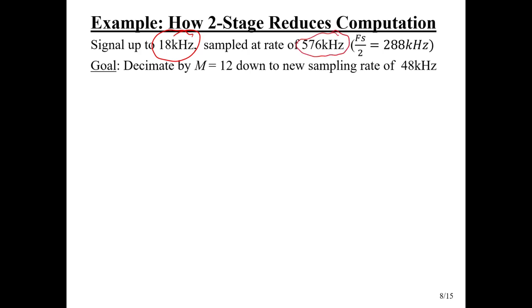And like I said, there could be any number of reasons why we have it sampled that fast. Could be coming out of a sigma delta A to D converter, and at the end of that device, it needs to be decimated back down to the regular sampling rate. Or it could be we're implementing some serious nonlinearity to get some distortion effect for a guitar.